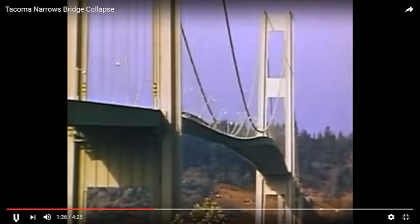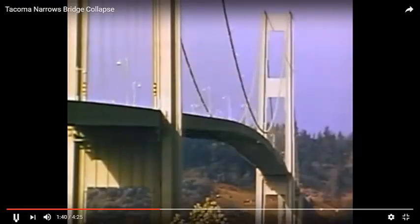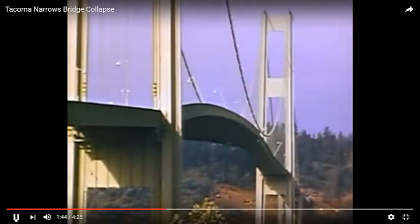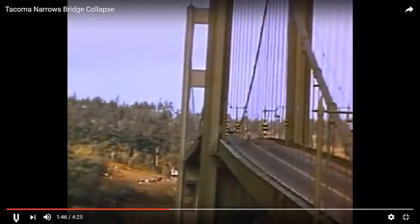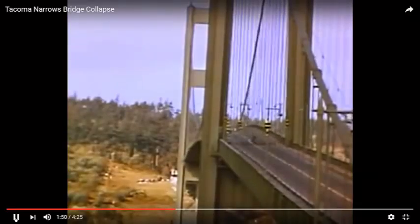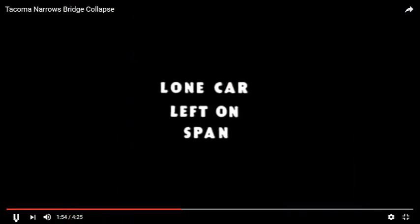So now you see this is a real life resonant condition, and to avoid any structure from getting resonant, we should know first what is the structure's natural frequency. Once you know the natural frequency and then the loading frequency, you can avoid this type of situation, resonance.